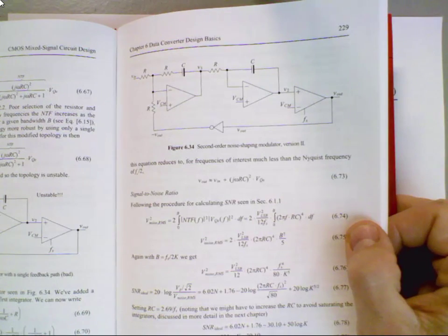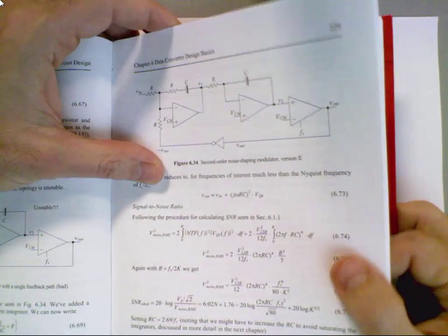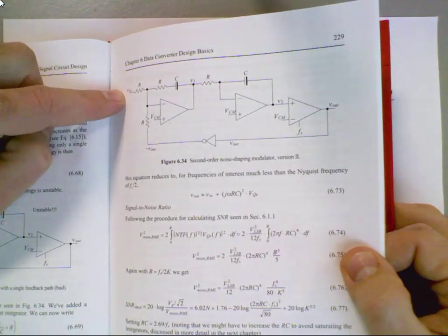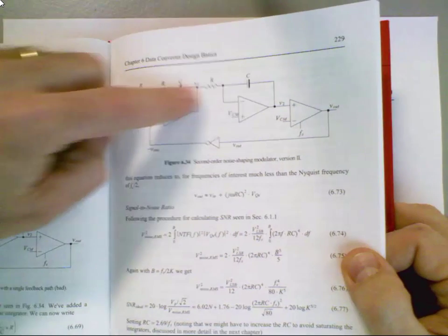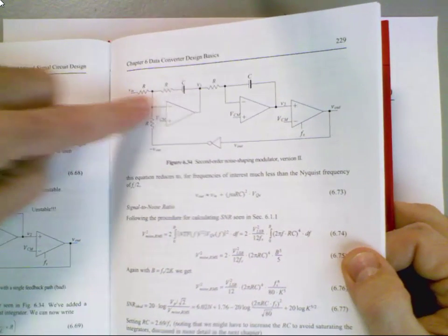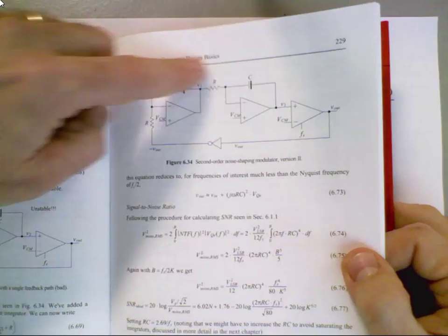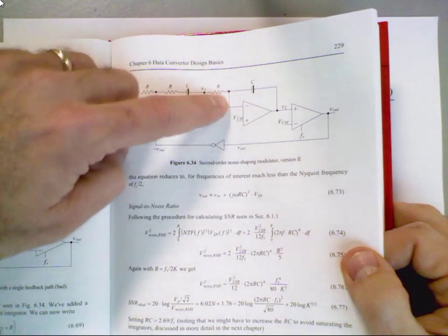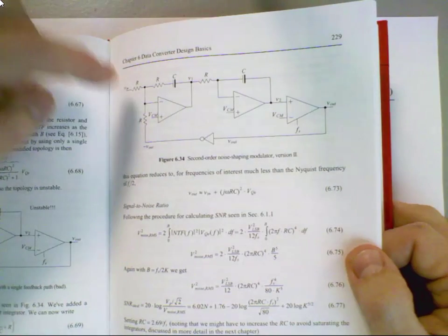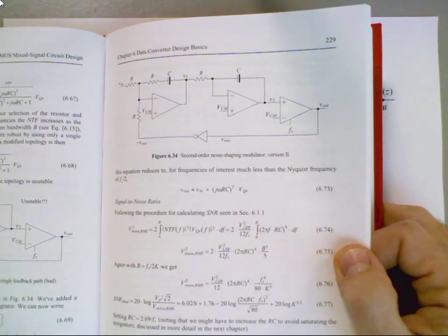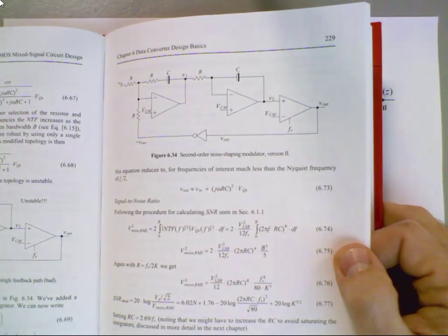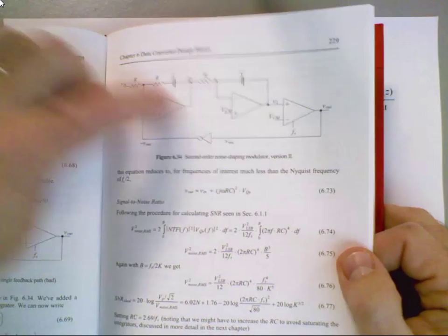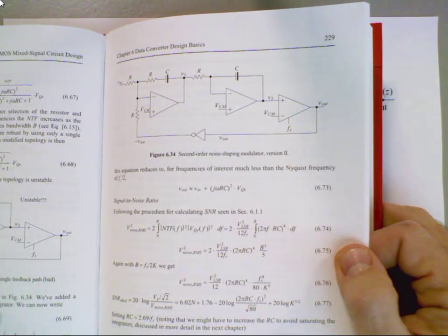Oh, okay. Well, what you might try, but again, you have to think about this because this stage is inverting, is you might connect your input in and feed directly into this point. So you have to derive the equations for it, but feed directly into this point to bypass the delay of the first integrator while still getting kind of second order improvement, and I'll talk about that more.